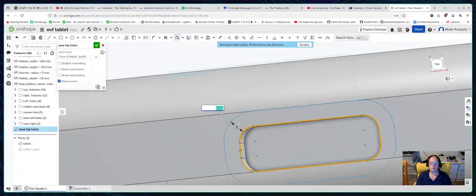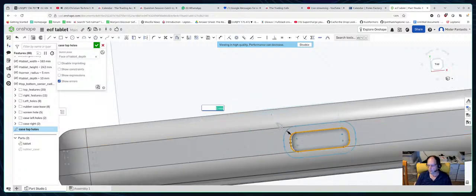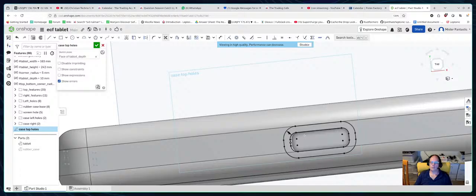Change it to 1 mil. And that's going to be the target hole. Yeah, so that'll be the target hole, and then we can delete this. Why is this 1 mil still selected? Okay, and then we can go to trim mode and delete all of that.